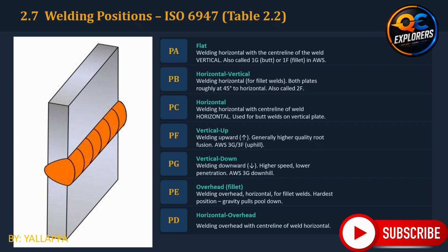PF is vertical up welding. The weld progresses upward, and this generally allows good control and penetration when the process and parameters are appropriate. PG is vertical down welding. The welding progresses downward. This can provide higher travel speed and productivity, but penetration behavior differs from vertical up welding.